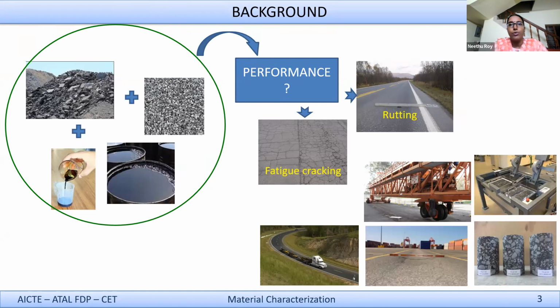Okay. Now, how do you study the performance of a pavement structure? Essentially, there are various ways. The first and foremost, or the most typical or the correct way of doing it, is that you should go observe your pavement structure for years and see how it is performing, right? So you can have in-service pavement studies, wherein you see what is the actual loading conditions, what is the actual environmental factors, what is the actual construction, the layer thicknesses, the quality of construction, everything varies from site to site. And in order to get the correct information, you have to go and do a site study.